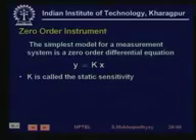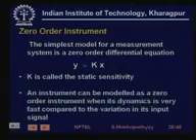So the input output ratio is linear, and this linearity exists from instant to instant, right? For such instruments there is no dynamics, and the static characteristic is the only characteristic that you need to see. Such instruments are called zero order instruments.